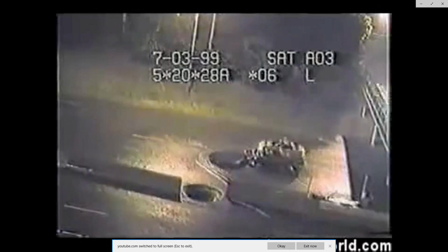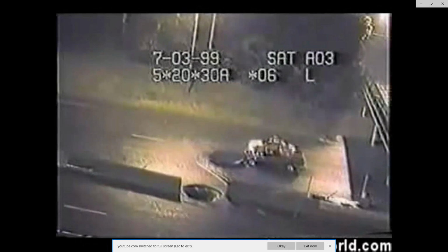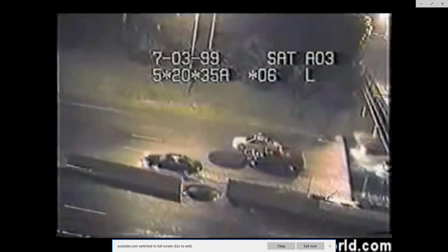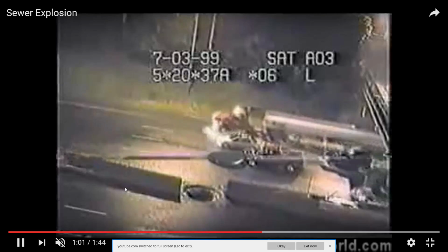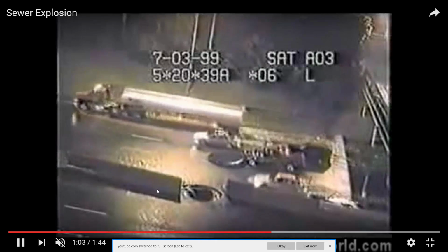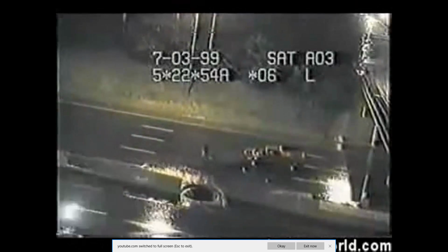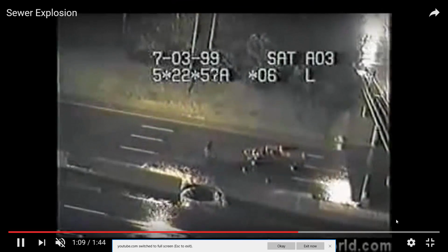All right, so what happened was that the pipe became surcharged, as it's called. That means that it's supposed to be gravity flow, but this may be a low-lying section of the pipe network, and there was so much water coming into other locations that it pressurized a section of the network.